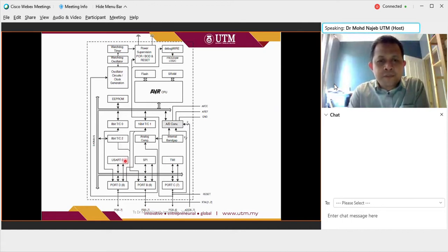But microprocessors and microcontrollers have the USART or UART module. This is in the format of a COM port, we call it serial COM port, and therefore on your Arduino board, if you look carefully, there's a UART to USB converter, right?